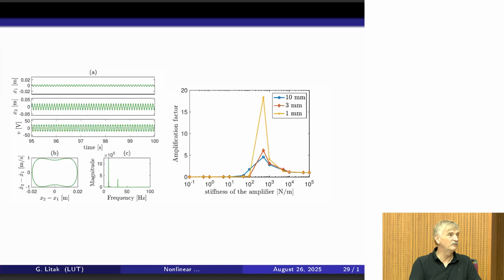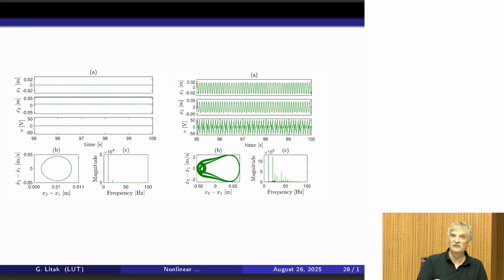So can we tell that the response is quasi-periodic? Quasi-periodic could be possible. However, you see that the problem is that we have so many peaks. But quasi-periodic is that you have, for example, two peaks, but if you divide one by the other, it is a non-rational number. Yeah.